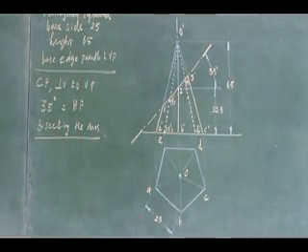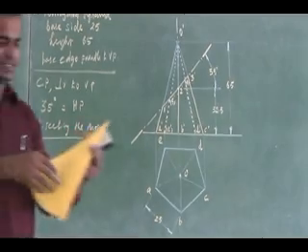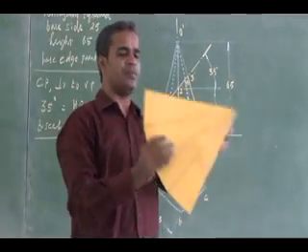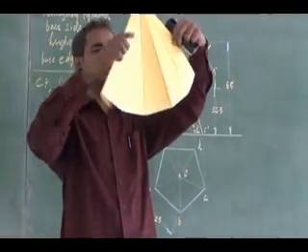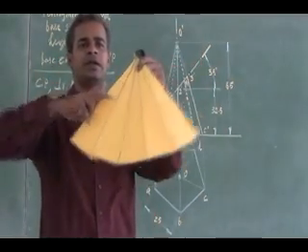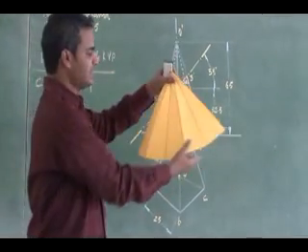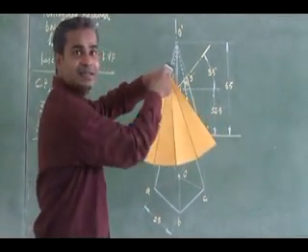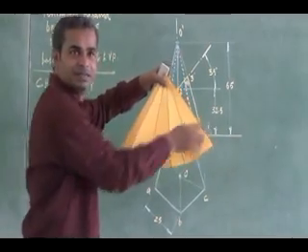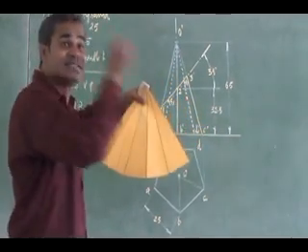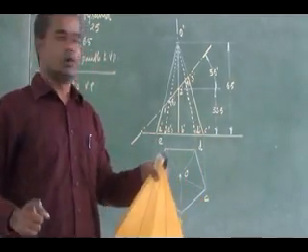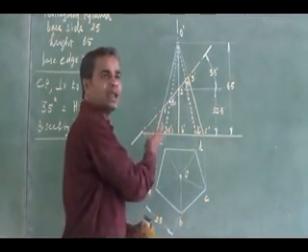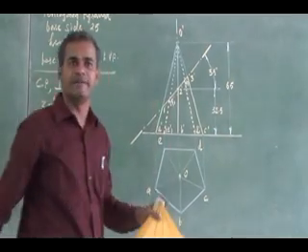You see here, this is going to be the development of a pyramid. Say I have 6 sides, this is the development of a pentagonal pyramid. Right? So for this, what I need, what is this length? This length is nothing but my slant length, that is exact slant length, true slant length. So do you have a true slant length in this orientation?